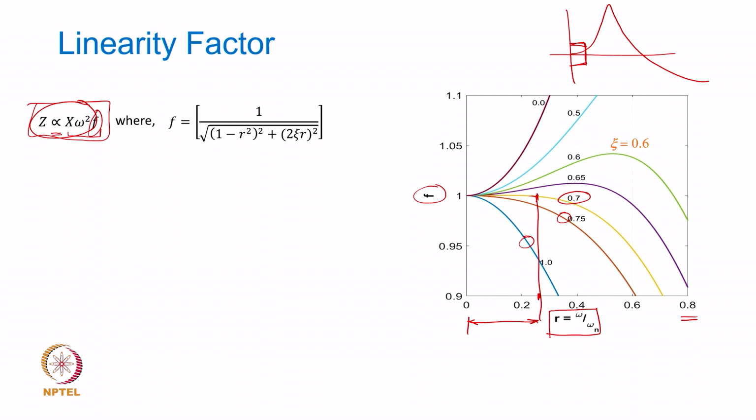So, the problem now is what happens if you go beyond this frequency range. Of course, if you go beyond that frequency range, the linearity is no more valid, and then you cannot have an accelerometer measuring different frequencies without making an appropriate scaling to the value that is output, right.